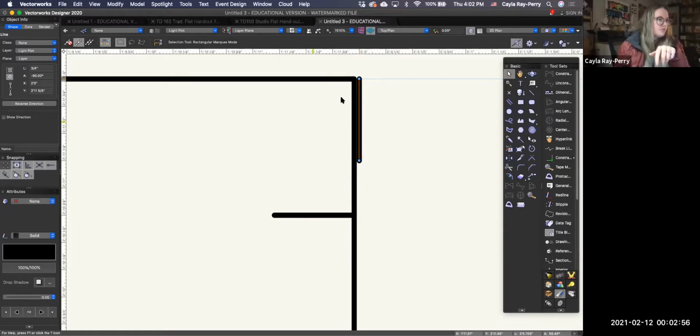Snapping, maybe I want that one. Is it snapping? Yeah, okay. So by turning that snapping off, it made it much easier for it to move away from this grid line. So this is snapping to the grid, which made it want to be right here.